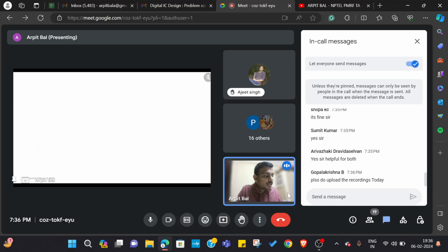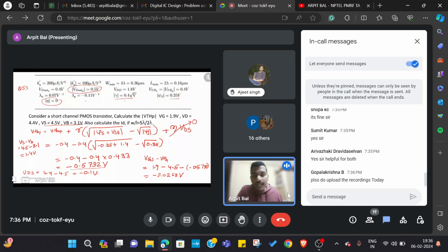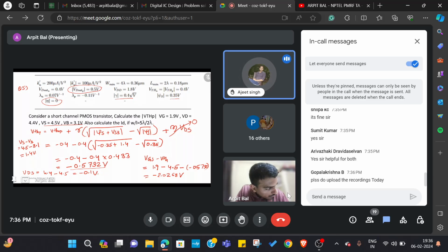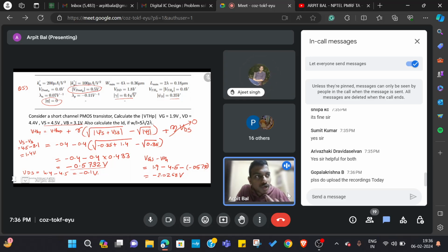It is based on your convenience. So I write it as plus eta VDS, and you just need to figure out what is going to happen to your VTH if your VDS increases. Sir, it means our VTH should decrease if VDS increases. Yeah, if it is an NMOS, true. Sir, in PMOS also it should decrease, but in negative value, by taking the sign. Yes, correct. If it is going to be more negative, then it means this particular sign should be negative, right?